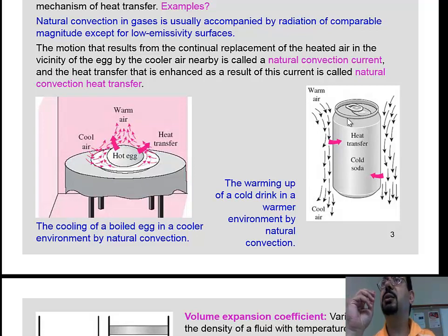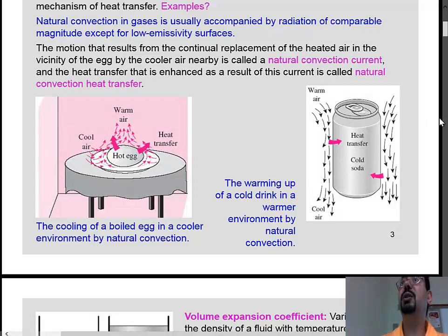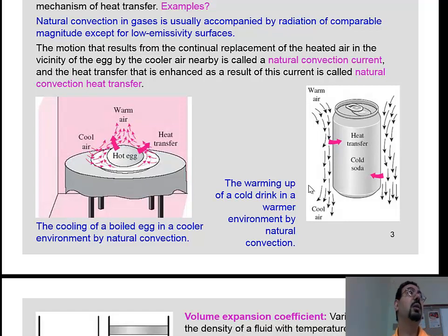The idea was convection basically increased the heat transfer by always changing this boundary layer. And so the V was really what's doing the trick, or the Reynolds number, because that was moving the fluid. So now in natural convection, yes, also the movement of the fluid will improve the heat transfer. You are changing the fluid, but there is no fan, there is no pump. The reason why those guys are moving is just because they got lighter, and that's why they go up.